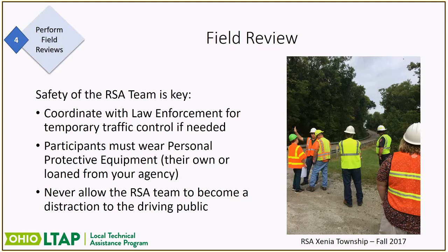Now, one of the things is you've got to make sure that you ensure the safety of your RSA team before you ever head out in the field. It's important to coordinate with law enforcement for temporary traffic control if it's needed. On this one we did because there were some sections of the road where we wanted to get out and look at intersections in a very rural area. So we had members of the Greene County Sheriff's Department that were out there to make certain that our team was going to be safe and do proper temporary traffic control.